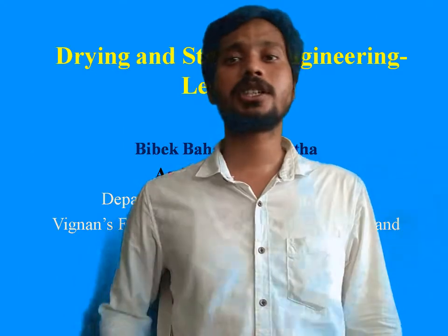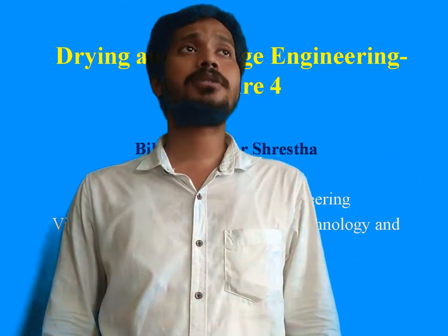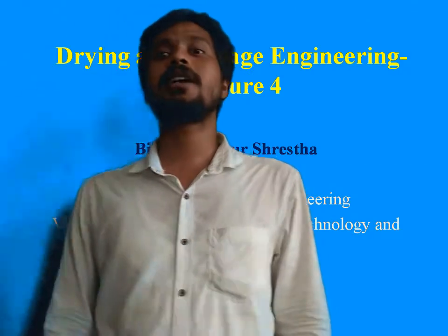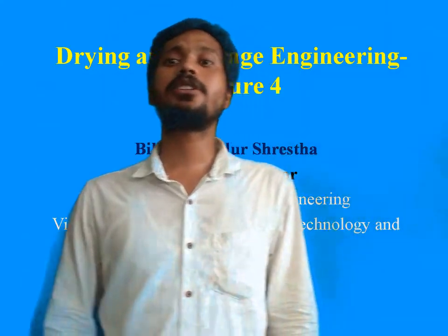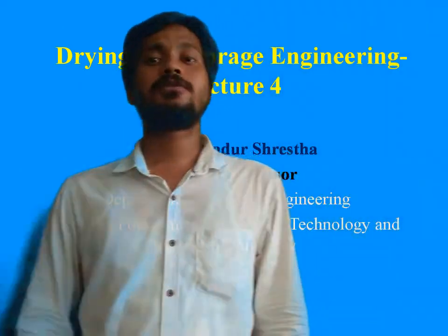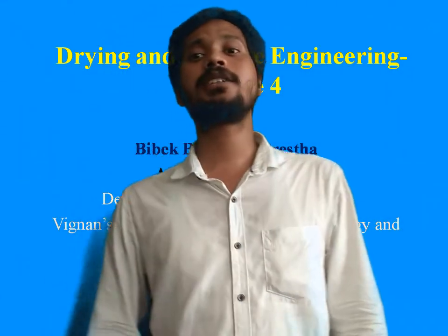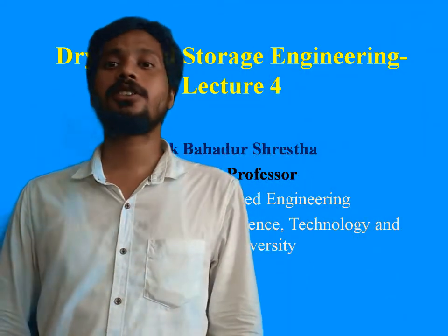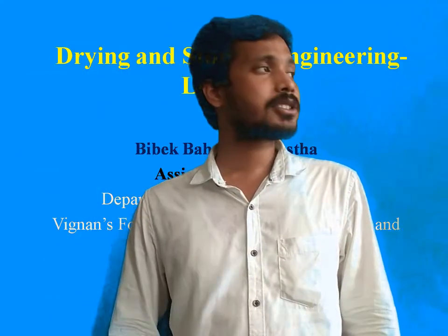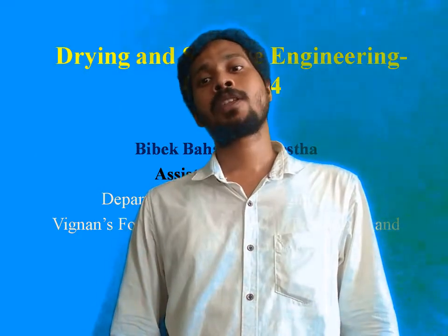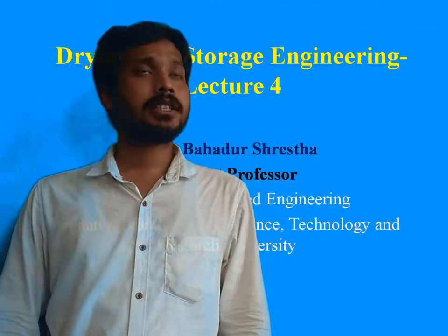We know the formula of constant drying time is (m0 minus mc) by rc, whereas the falling drying time is mc by rc times ln of (mc by m). Both values of moisture content will be in decimal and in dry basis, and rc is the constant drying rate in mass of moisture by mass of solid per second. So up to this we discussed.